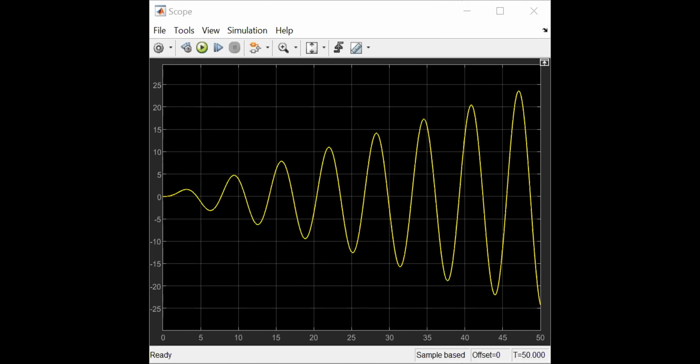The system started with 0. The amount of time the system took to get to 2/3 of its steady state response, and this is the point, 2/3 of the steady state response, is called the time constant of the system.